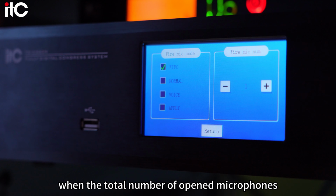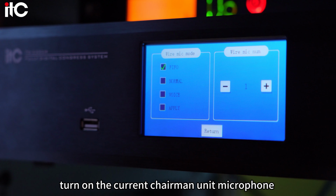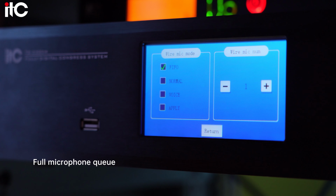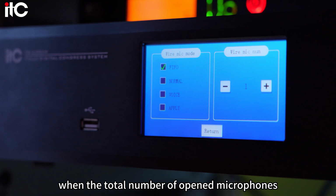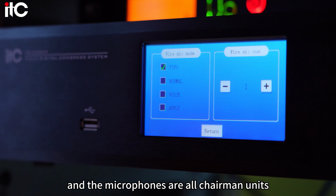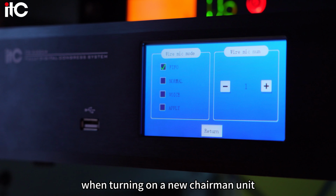When the total number of opened microphones reaches n, and there are some delegate units, turning on the current chairman unit microphone will kick the earliest delegate out of the microphone queue. Full microphone queue. The chairman units are not restricted by FIFO mechanism. When the total number of opened microphones is n, and the microphones are all chairman units, it will display full microphone queue when turning on a new chairman unit.